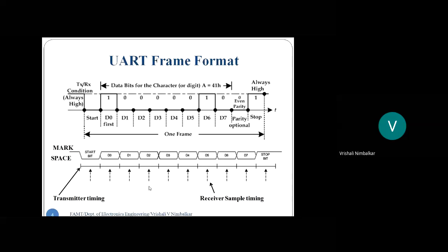And one more thing, in serial communication, logic 1 is also called the mark bit. Few technical names have been given. Right? So logic 1 is called the mark bit and logic 0 is called the space bit. Just some technical names too. Okay, so this is the UART frame format. And that's a technique for transmitting and receiving the data. Fine. Universal means everyone in the world is going to follow this frame format, this transmission and reception technique.